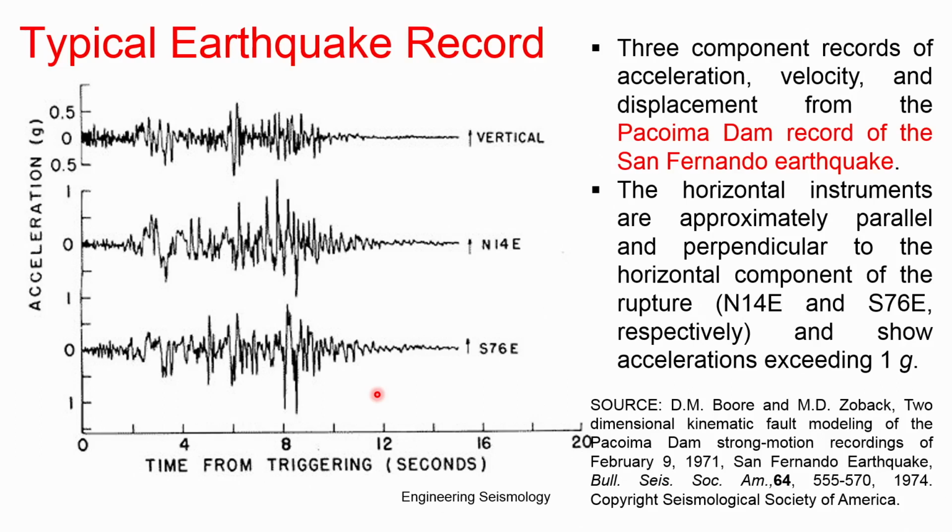These are all the information one should keep in mind when processing and trying to understand the earthquake. For the same earthquake recorded at the same distance elsewhere, the station may not be oriented towards the fault directivity, and you will have less acceleration or velocity value. So, this kind of directivity also influences the seismic record.